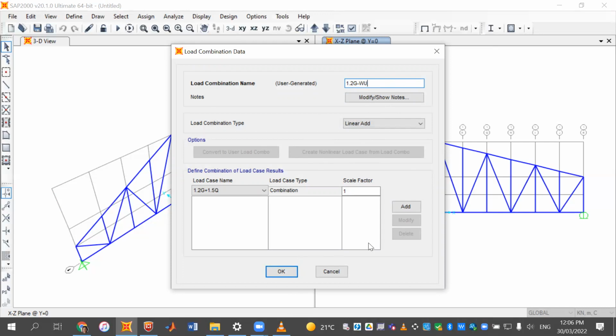However, if you are going to add your internal and external wind pressure on your roof at the same time, it means you calculate the resultant of internal pressure and external pressure, that would make it wrong.